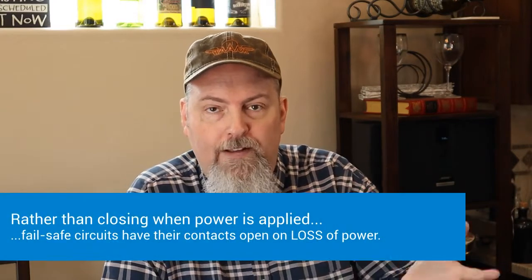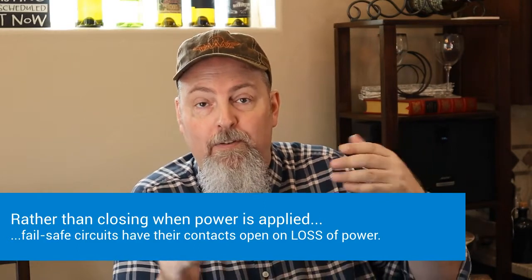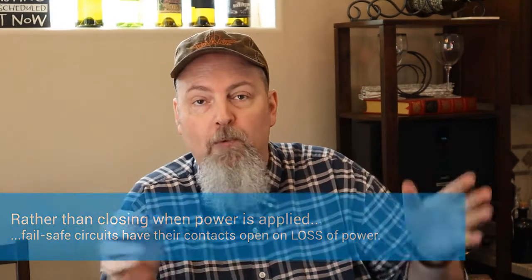If you look at page 9 on your text, under failsafe features, paragraph delta, it says the opening of the contacts to a relay, which initiates a scram, is what a failsafe circuit is. That is, the power side of the RPS system, the reactor protection system, holds those contacts closed under normal conditions. Because if we have a complete loss of all AC and DC power, we don't want to lose our ability to monitor our logic circuit and not have a scram if something happens.